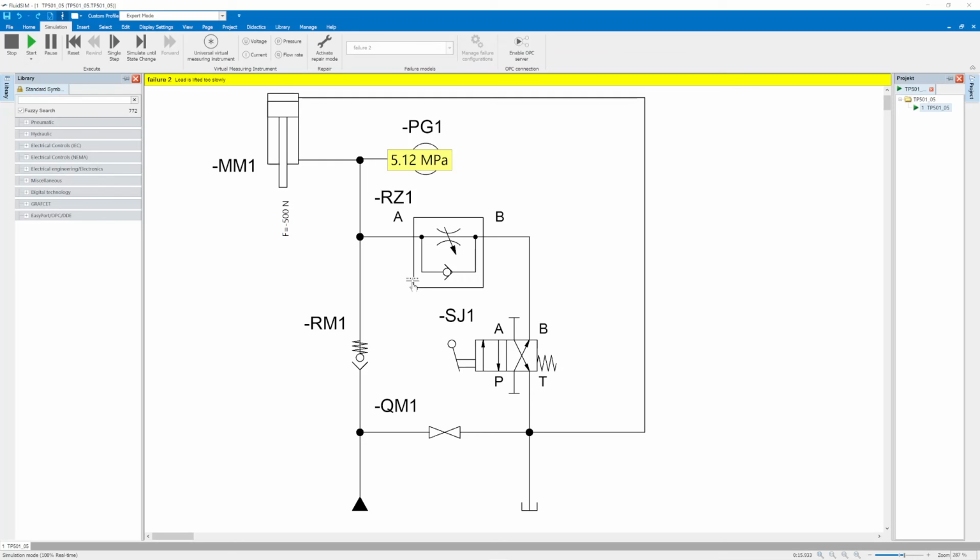The virtual gauges can be activated in the simulation menu in the Virtual Gauges section. There are gauges for pressure, flow, voltage and current. After clicking on the desired measuring device, the crosshairs on the mouse pointer indicate the position of the display of the measured value, which is defined with a mouse click. The probe tips can then be placed on compatible terminals in the circuit. As soon as the measuring tips are placed, the measured value is displayed.